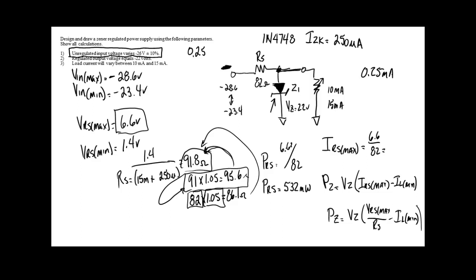But they never calculated the resistor. And this is something we probably need to teach way down there, where when you buy that resistor, you got to know 3 things about that resistor when you buy it. And what's the 3 things? The value, the watts, and the tolerance. You got to know that. And what things do we need to know basically about the Zener? We need to know 3 things about the Zener. Not the physical size. VZ, right, you understand, the wattage rating, and the tolerance.